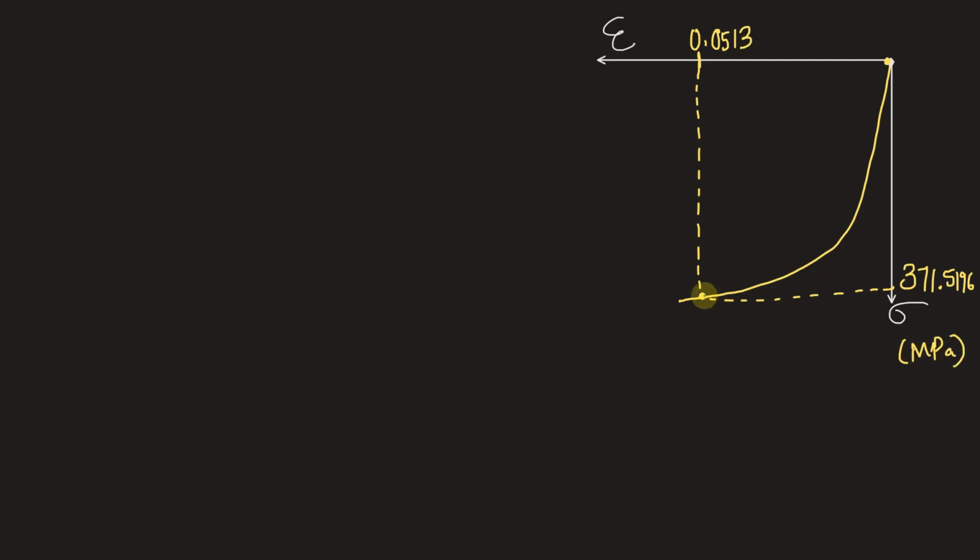Now after it is recovering, it will follow the slope of this initial elastic curve, slope of which can be found out using Hooke's law. So these lines will be parallel to each other when there is the elastic recovery. This being a right angle triangle, if you want to find out the strain that is being recovered, we can find out using Hooke's law, isn't it?